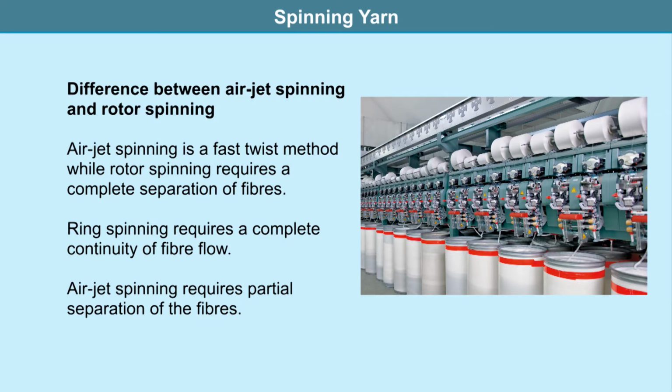And in air jet spinning, the slubber or the simplex is eliminated because the cotton is fed into the machine in the form of sliver rather than a roving. Large tubs of stock taken from the drawing process to the spinning department reduce manual handling. The yarn discharging from the spinning head can be wound directly onto spools to eliminate the need of a winding operation. So that is the advantage. Even in the rotor spinning, this facility is there of winding the yarn onto a spool, so that further winding, like in the case of the ring yarn, could be eliminated.